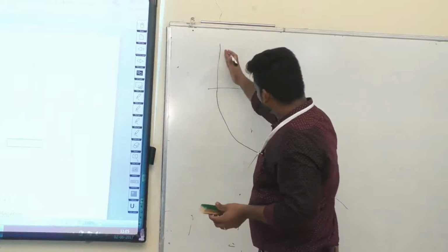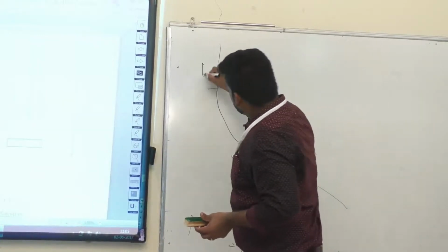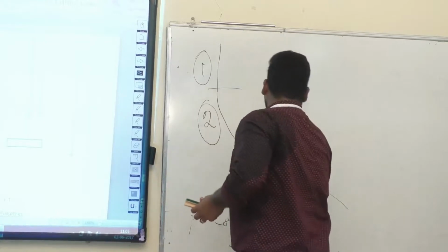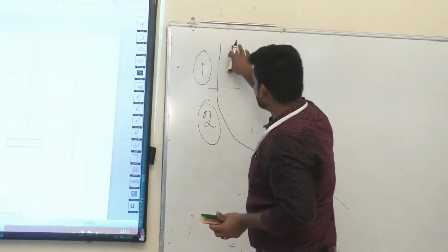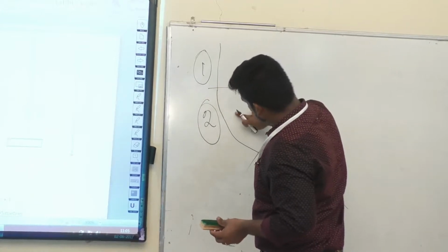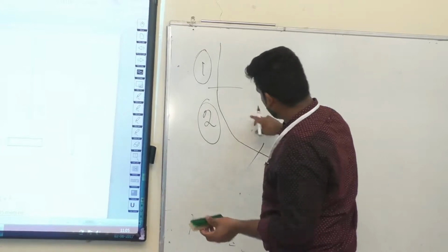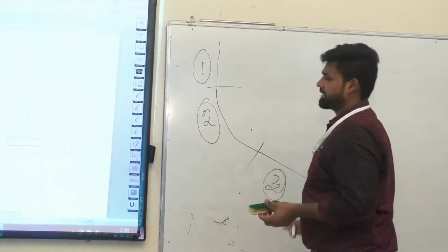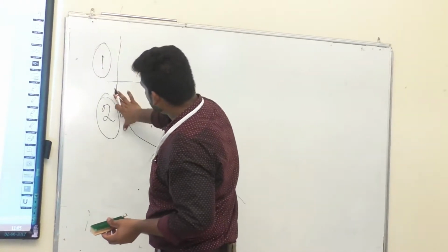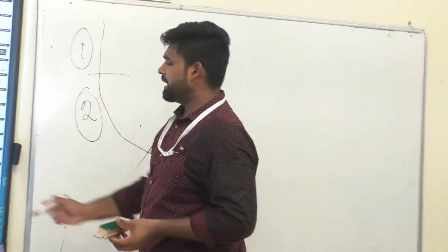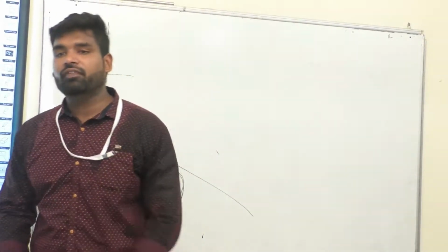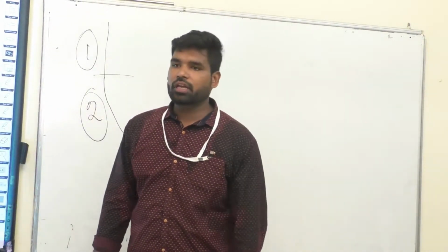So what is the total length of the borehole? It is the length of section 1, the length of section 2, and the length of section 3: the vertical section plus the measured depth of your build-up section and the measured depth of your tangent section. So that is equal to 200 plus L plus T, that is 8,748.95 meters. Are you clear with this?